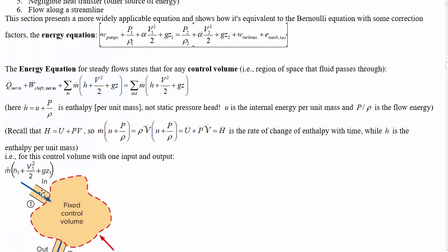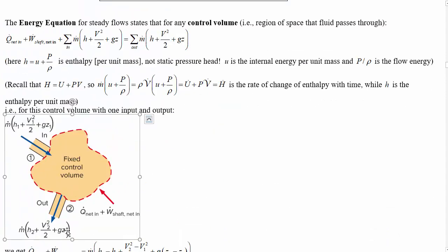It starts with a control volume. We're going to apply the first law of thermodynamics, which is, that's right, energy conservation. So the total amount of energy we're putting into this must equal the total amount of energy we're pulling out of this control volume. Control volume just is a concept for an imagined section of fluid. So we're going to say, let's look at this one amount of fluid, and let's say the volume of this can't change, then that's what the fixed is talking about.